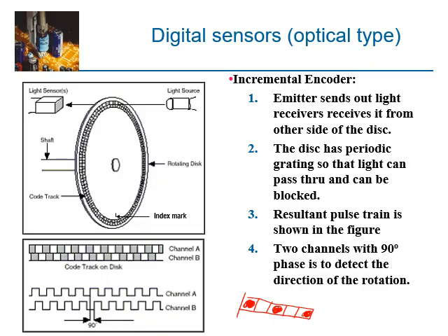The sensor is attached to the microcontroller. Now, if you start to count this number of pulses through your microcontroller by triggering a counter, then you know how many counts the wheel has rotated. You can calibrate this rotation with this number of counts. Usually one whole rotation will give you 2000 pulses. So in one whole revolution, you will have 2000 pulses.